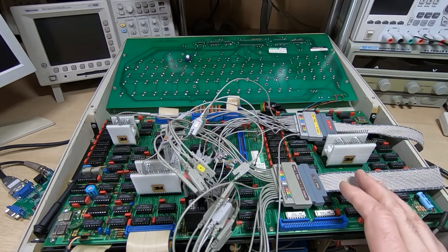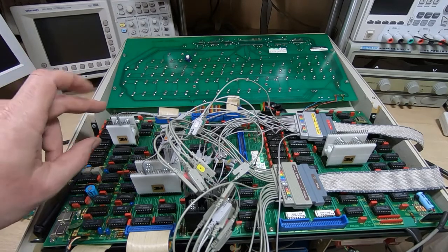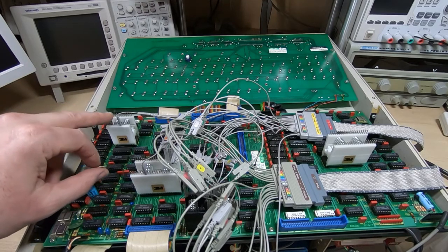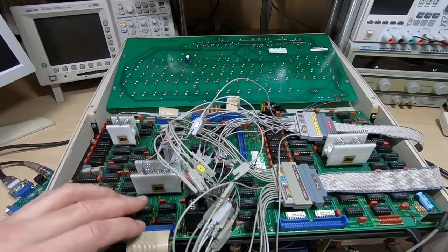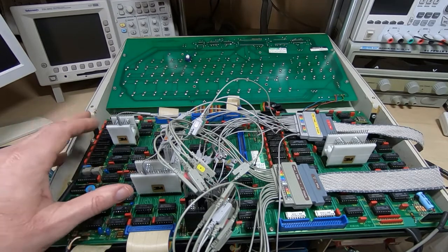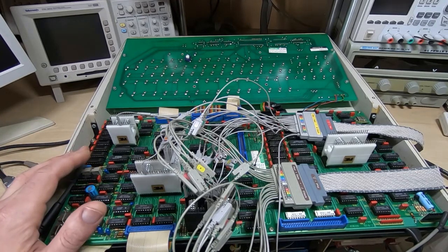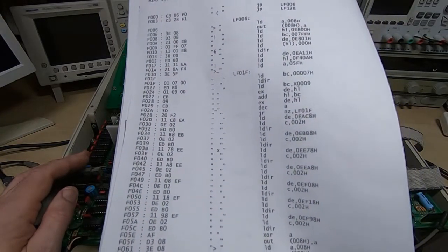It's not working on this machine, and the approach I've decided to take, partly to make some videos but also of course to try and sort out the problem with the machine, is to reverse engineer the code that is in the system ROM. It's a very simple system ROM on this machine. It really only consists of the bootloader to load data from the floppy drives into RAM and a very simple monitor program. What I've done so far is extract the data from the ROM and turn that into a disassembly